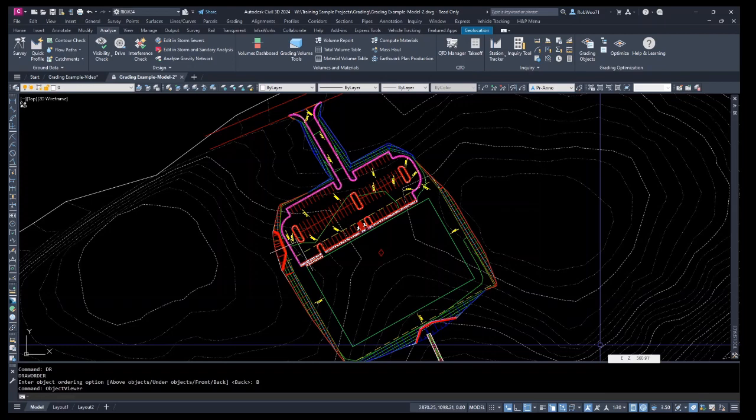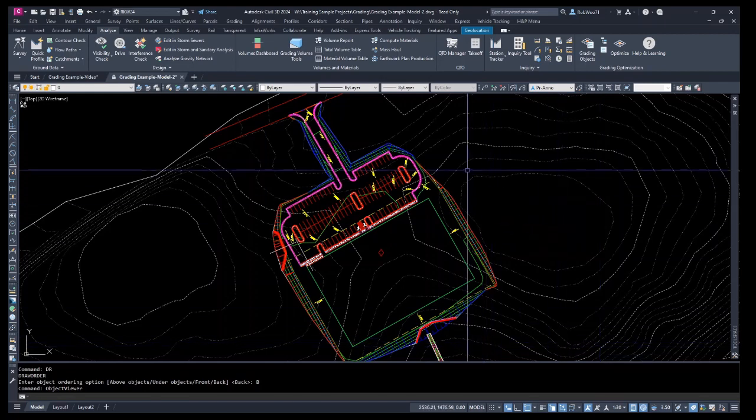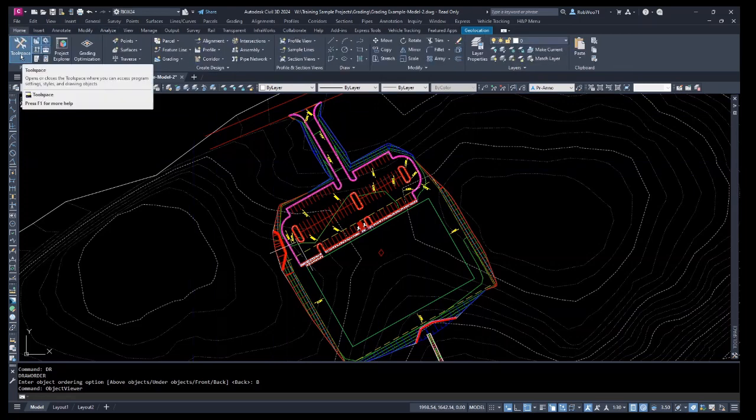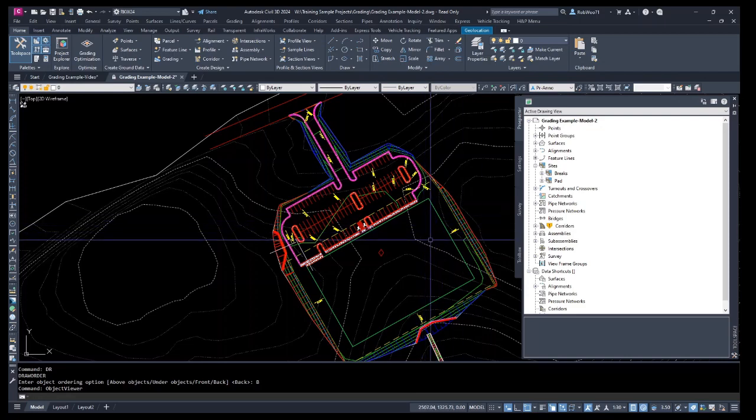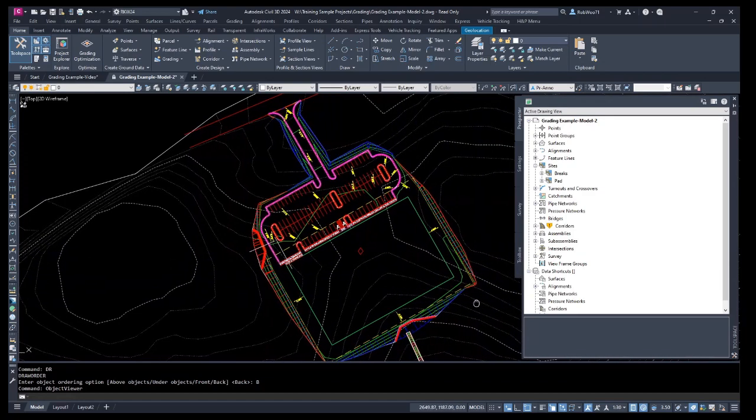I just used this example and this approach to show that creating feature lines and putting them into a different site helps you manage that interaction between feature line, grading object, corridor, and auto corridor feature lines, and how they can all come together to create one composite surface that's interactive and can help you speed up your process for finding a viable grading solution.